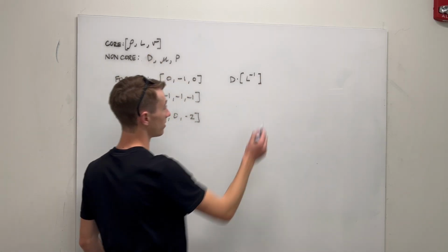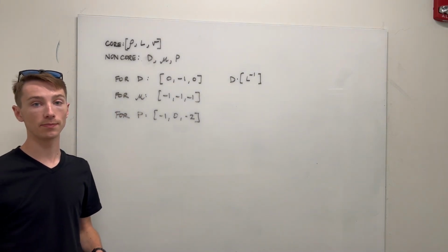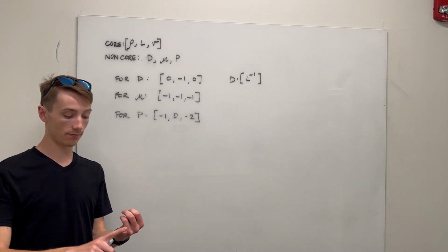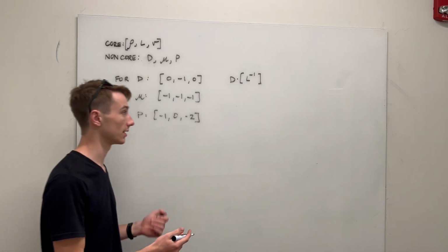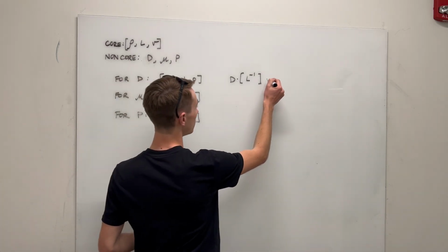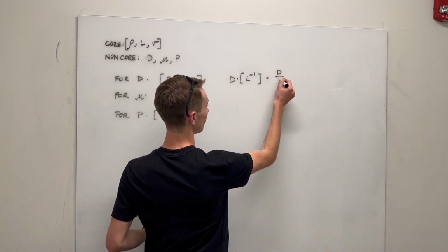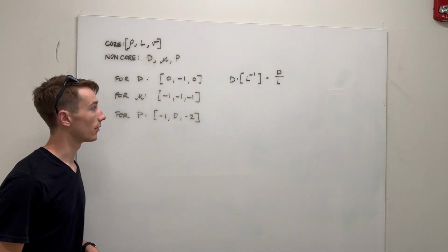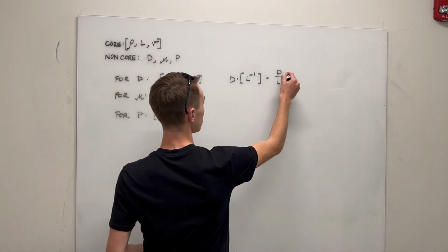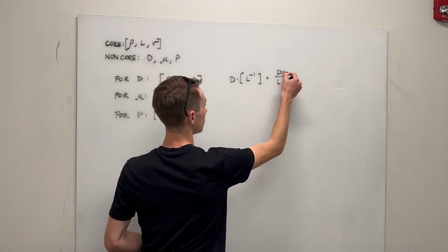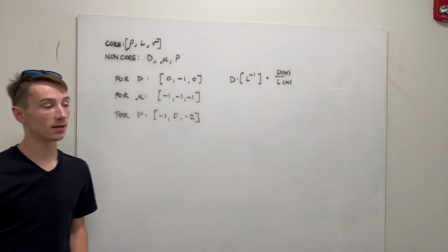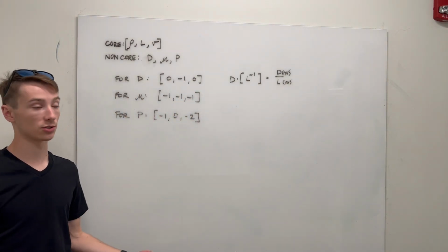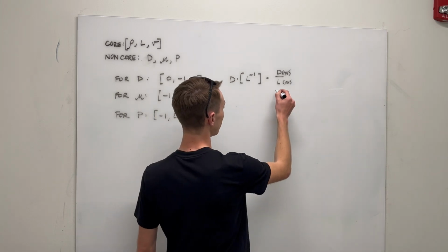That's a dimensionless group because the powers of the mass, length, and time of that final unit add up to 0. Let's see what it works out to. So this is d over L, right? We know that diameter is in meters and length is in meters. And look at that, our units cancel out. That's a simple one, obviously. That's our first dimensionless group, d over L.